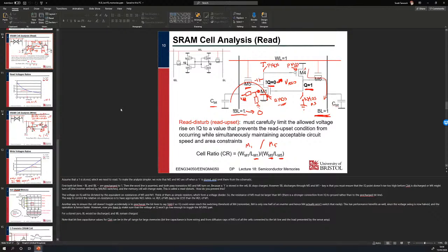No, they are different from a flip-flop or a latch. A flip-flop is edge triggered, and a latch is value triggered. With a flip-flop, when it sees the rising edge of the clock, it catches the data. With a latch, you could consider this somewhat similar to an SR latch, because we just put the correct set and reset values on it to write the data to it.